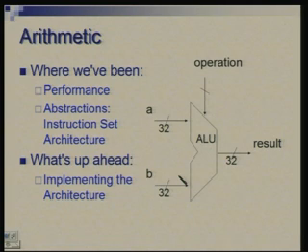So, essentially what we are aiming at is designing something like this, an ALU, which typically works on 2 operands. In our case, for the MIPS processor, these will be 32-bit operands, and it produces a result under control of some signals which are determined from the instruction. So, depending upon which instruction you are trying to execute, this unit will perform some operation. It might perform addition, subtraction, multiplication, division, or do some comparison, or some logical operation. Okay. So, in the next few lectures the focus would be the design of this.